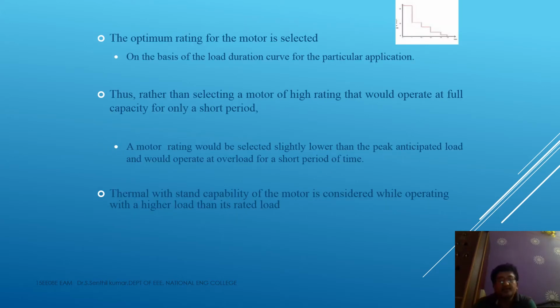And while choosing the rating of the motor, we have to calculate on the basis of the load duration curve for the particular application.